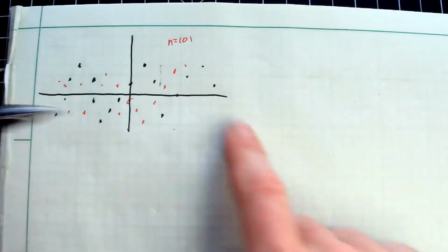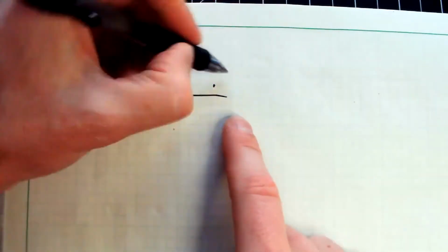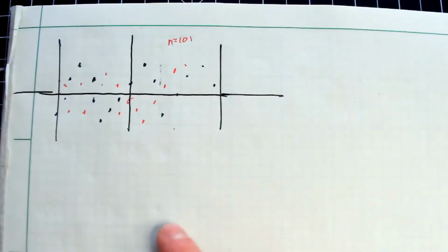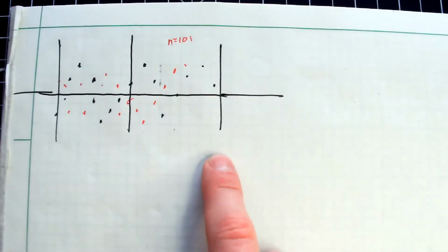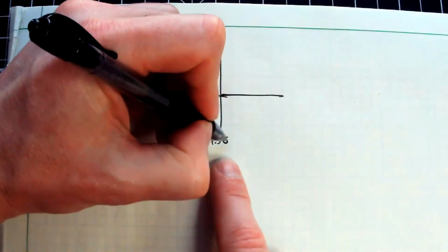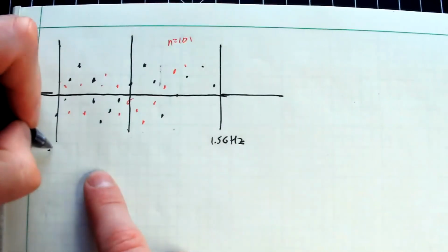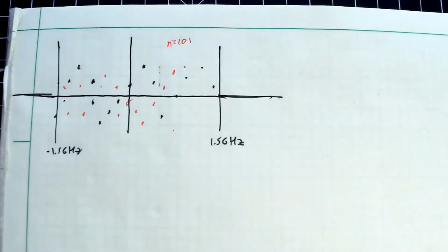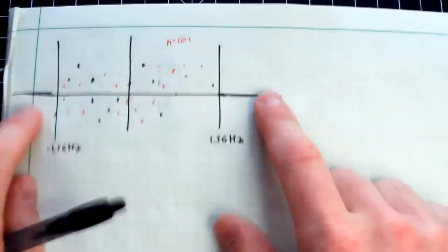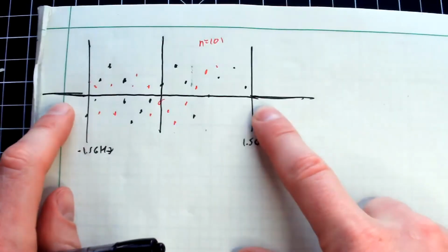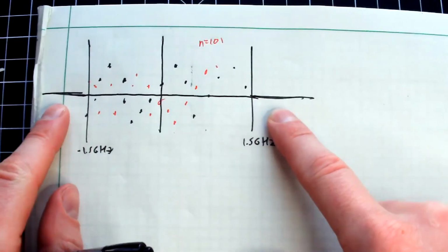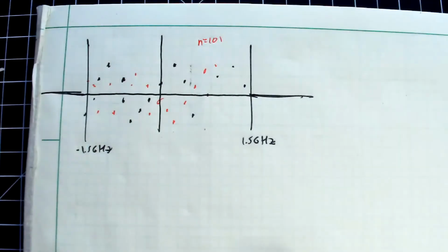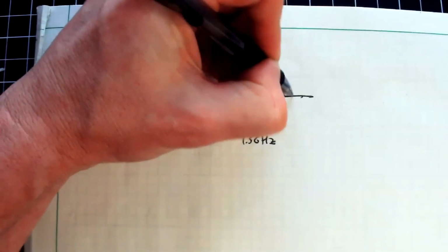And then what's essentially happening is you have these walls here where everything is being zeroed off. So I have a bunch of samples out to some fixed bandwidth, say 1.5 gigahertz here, and then negative 1.5 gigahertz. And then it's just zero on forever after that. So the problem was we didn't actually include these zeros in our samples in our Fourier transform. We just stopped right there. So the way you can cheat this is just pad your array with a bunch of zeros.